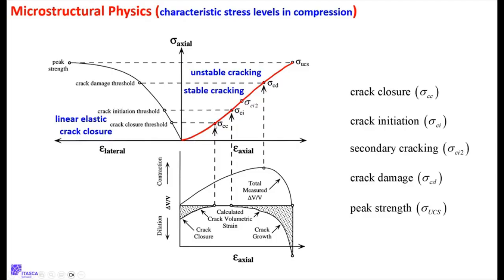The slopes here, which are E and nu, will have a very small variation. It might be 69, anywhere from 65 to 74 GPa. So the elastic stuff will be almost the same, but for the peak there's going to be bigger variability. It might be 200 plus or minus 30 MPa.